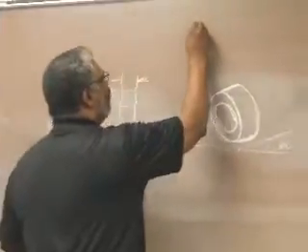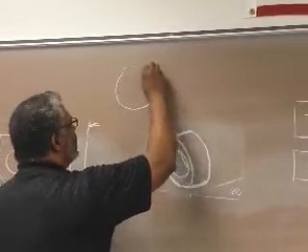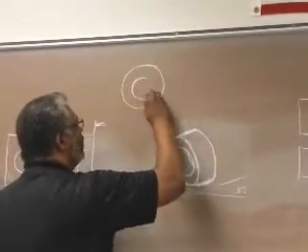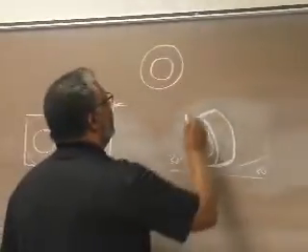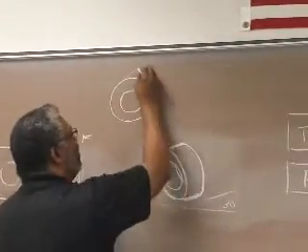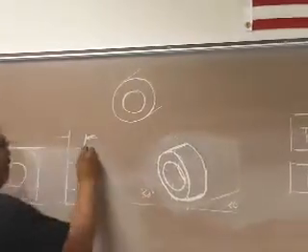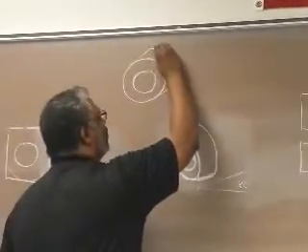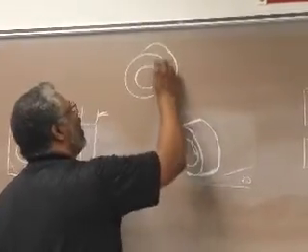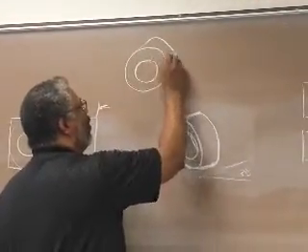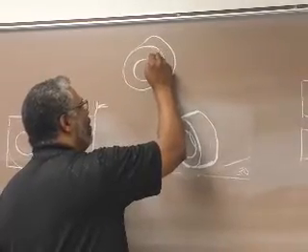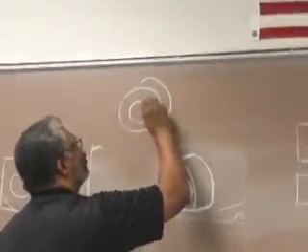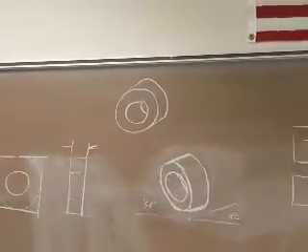If I were to do this as an oblique, I would start off with this as a true circle and with this as a true circle. As you see, not rotated or anything. Then I establish my tangent lines going back. Back here I will pick up the back portion of that, which is a true circle. And then I'll get a true circle for this here, so where that crosses, I'll see part of that as a true circle. And that will be an oblique.